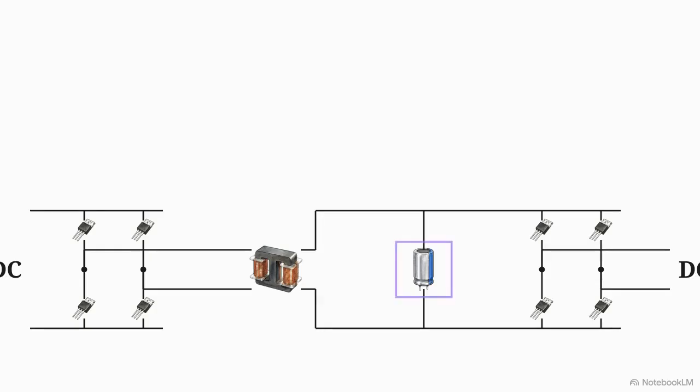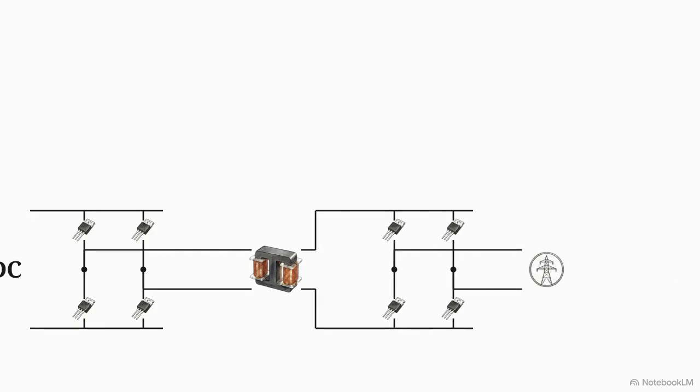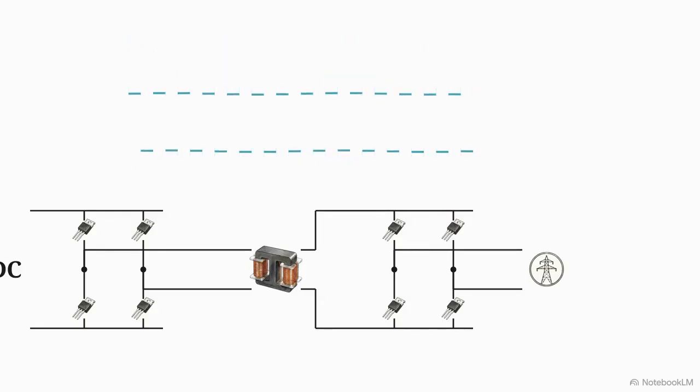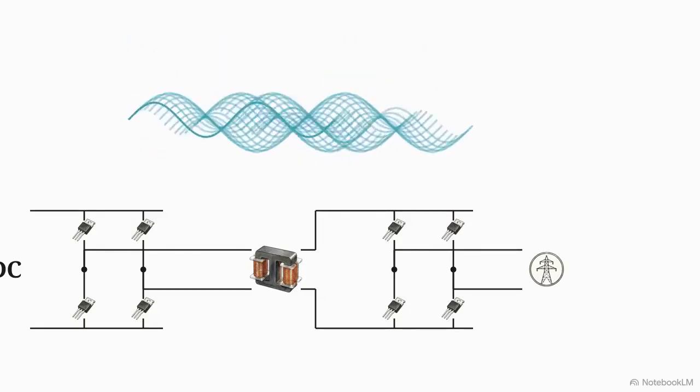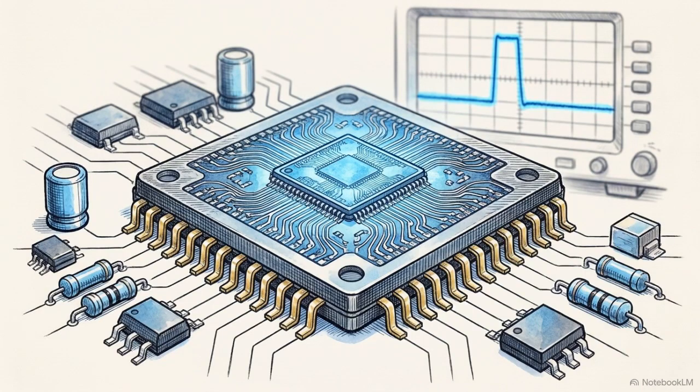We delete the intermediate DC link capacitor entirely and connect the secondary bridge directly to the AC output, creating a single-stage converter. This direct connection applies cycloconverter theory. Instead of rectifying the high-frequency transformer square waves into DC, it translates those waves directly into line frequency 50 or 60 Hz AC. Converting power at 100 kHz means managing switching transitions every 10 microseconds.